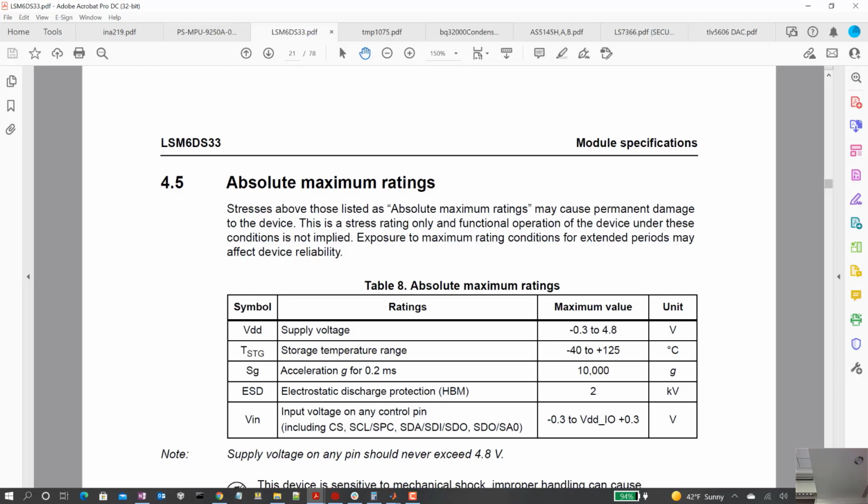You hardly ever see an I2C chip that allows you to set it to any of the 127 different addresses. Usually it'll hard code a couple of the bits of the address, and allow you to change a few of the bits of the 7-bit address. Does that make sense? Because too many pins, that would require what?